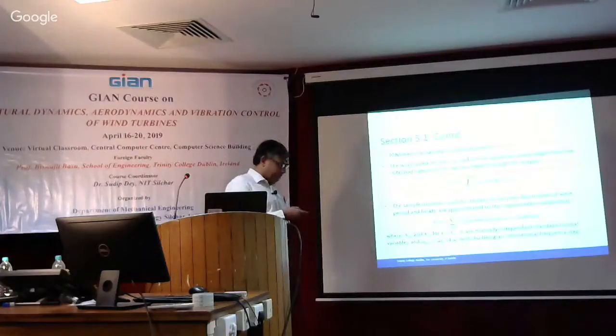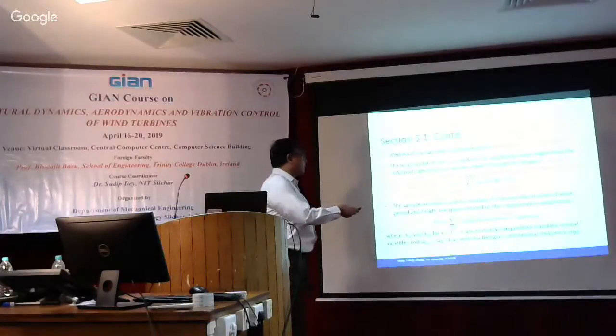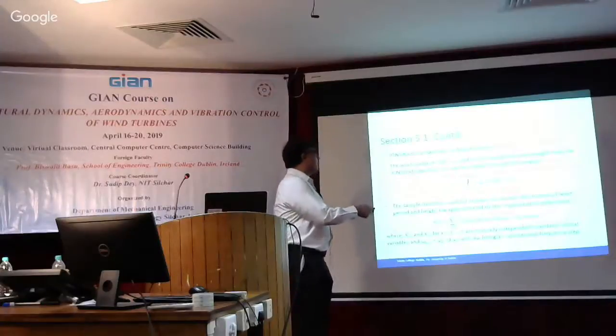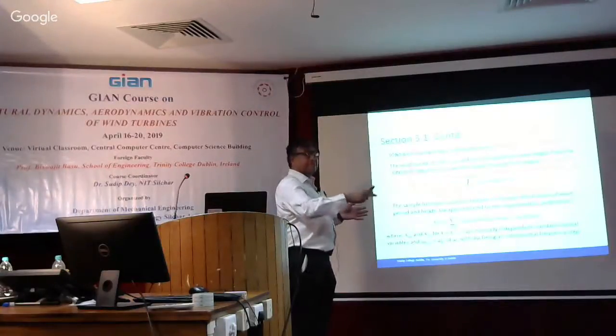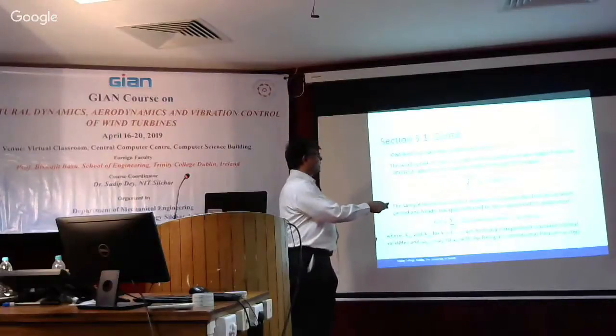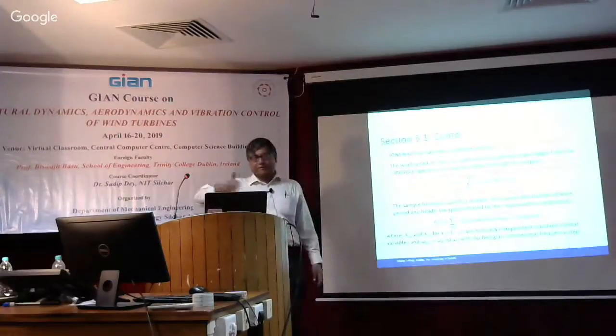And in this case, obviously, we are showing how the variance of the spectra can be related to this sigma square value, the zeroth moment, lambda 0. And the wave obviously has a height of Hs, and there are different frequencies, so that's represented in this spectra for different values of omega.